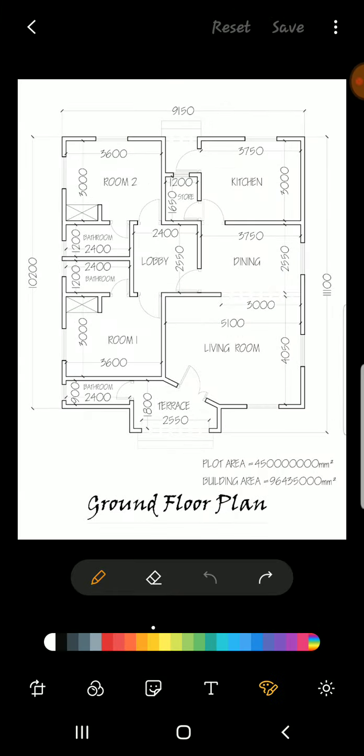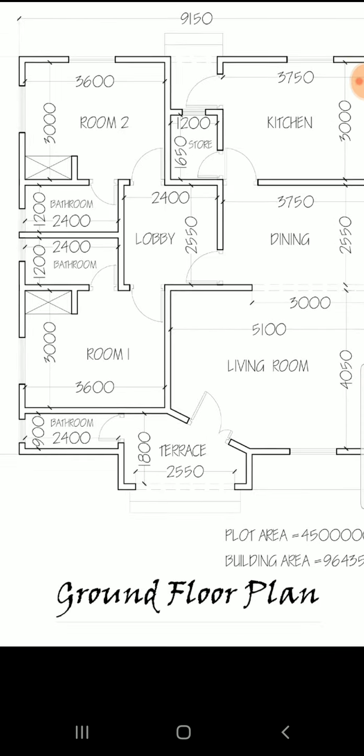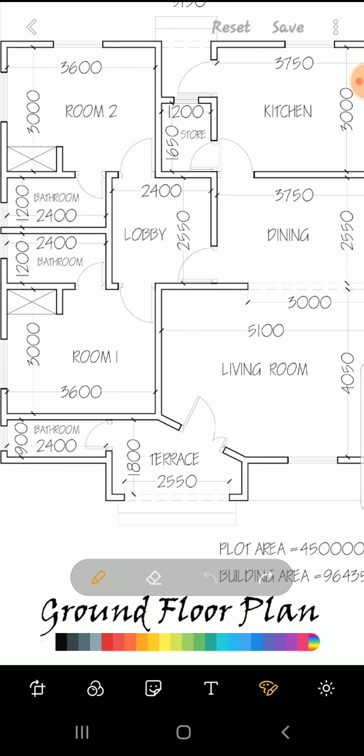Now how do we determine that? Let's go back to the plan. Here on the plan you have different areas, different kinds of doors. Now how do you extract these doors from the building? We have the standard door width as 900 mm. And then the width for your bathrooms is 750 mm. Here we have the width of the door leading to the living room, which is the main door of the building, as 1,200. So you can see that we have varying door widths, but there is a way we can determine the number of standard door widths that we need for this building.